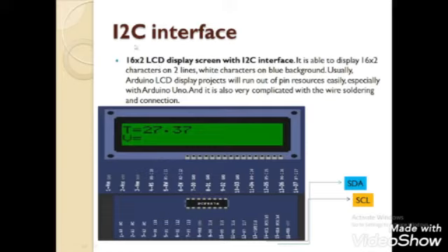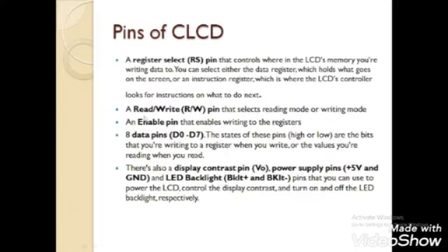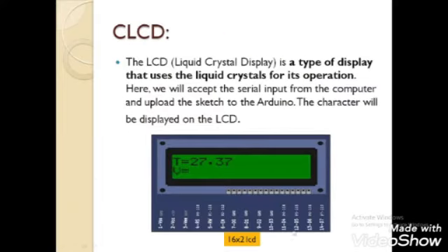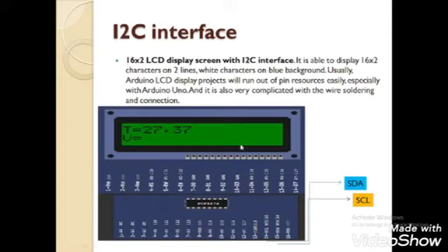So the I2C interface, what is the need of I2C? From the previous slide we can see that there are a number of pins that we must connect to the Arduino to display the data coming from the Arduino. But as per the requirement of this project, we have to use a number of pins of the Arduino, and the Arduino pins are limited. So by using this I2C interface, we will be reducing the pin requirements.